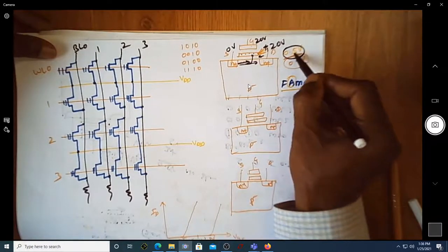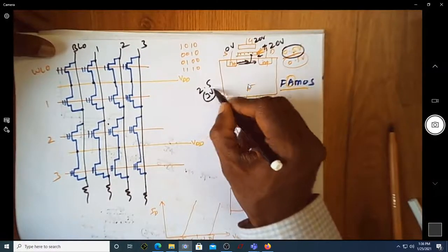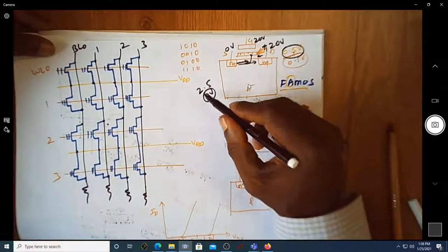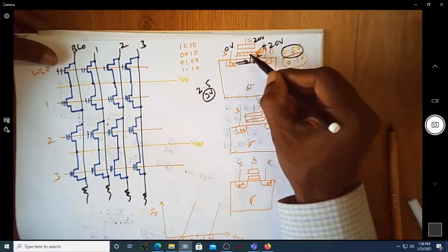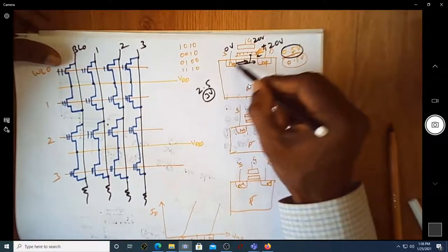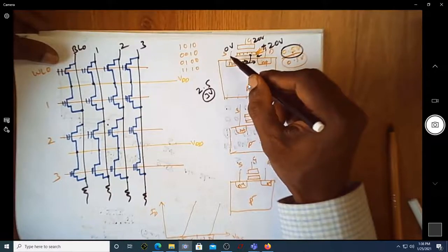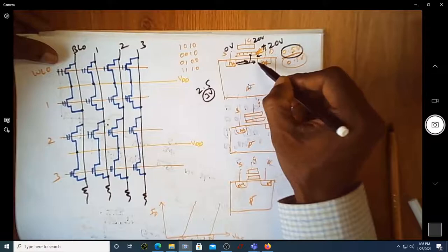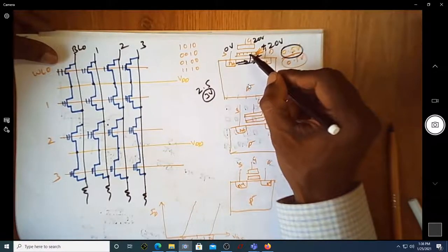As the number of electrons settling down keeps on increasing, the threshold voltage, which was 0.5 volt, will now increase to 2.5 volt or 3 volt. Why does the threshold voltage go from 0.5 volt to 2.5 or 3 volt? Whenever no charges are accumulated here, it was sufficient to have only 0.5 volt. Whenever you have electrons accumulated here, we know that electrons are negatively charged. So if you want the channel to get formed, we need to first overcome the charges that are there in this floating gate structure.